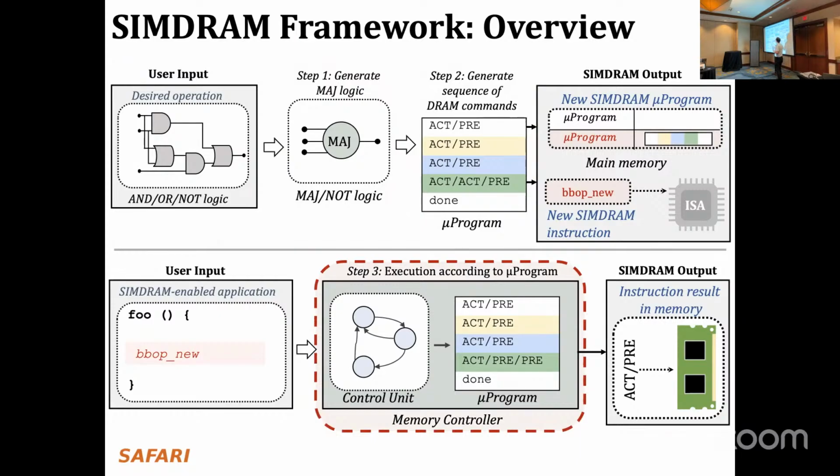Now, in the program, you insert these bulk bitwise operations, which is an issue, like who inserts this? We're going to talk about that in the next work briefly, but Geraldo will go into more. And when the operation is called, executed by the processor, it gets shipped to the memory controller, and the memory controller executes the microprogram associated with the operation.